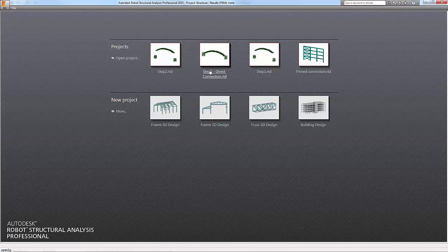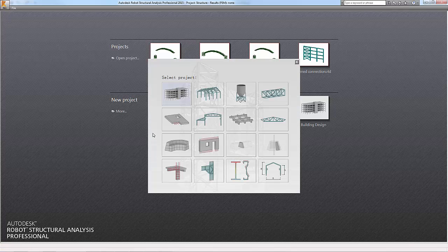Once we start, make sure the structure you put in is a 3D frame structure. You need to use this one, but don't use that one, because if you build the frame structure with that one, you cannot put the uniformly distributed load onto the structure. That's a drawback. Because we have frame structures and truss structures together, we have to use the frame 3D design and this type of model to create the structures. So let's click on this one.